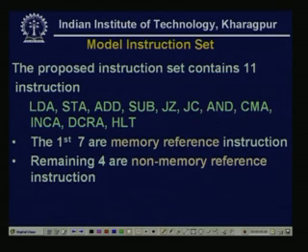Here the first 7 are memory reference instructions and the remaining 4 are non-memory reference instructions. That means LDA, STA, add, subtract, jump on 0, jump on carry and the logical AND are memory reference instructions.